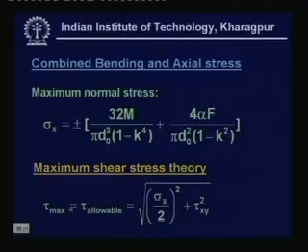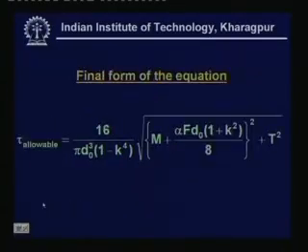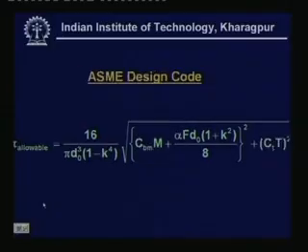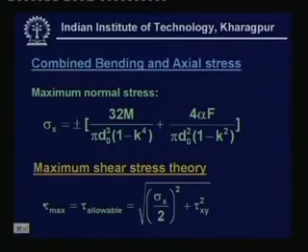That means, material strength in shear should not be lower than the maximum shear stress arising due to external load at that particular point, which in short defines tau max as the maximum shear stress, and this tau max is equal to tau allowable or the working, and that is given by the square root of (sigma x by 2) whole square plus tau x y whole square.